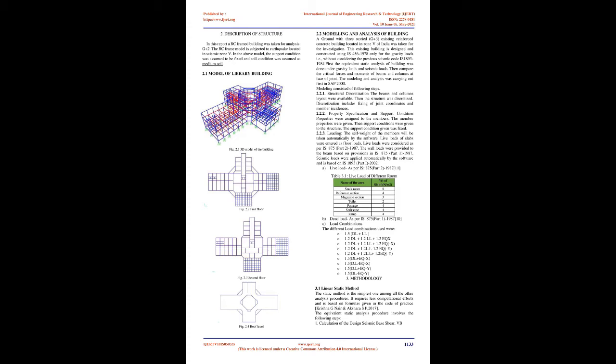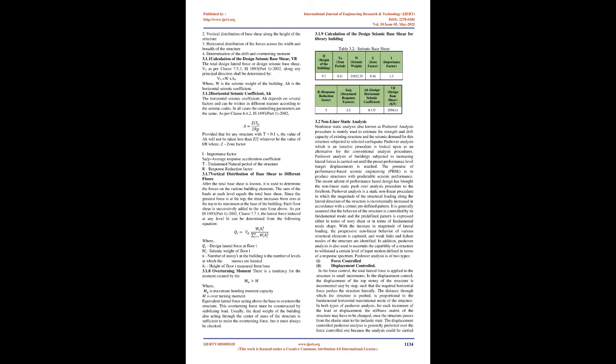In the conventional elastic design analysis method, many important aspects that affect the seismic performance of the building cannot be determined. The inelastic deformation of a building under seismic ground motions determines its structural behavior. Due to this reason, the evaluation of the building is carried out on the basis of the inelastic deformation demanded by an earthquake, besides the stresses induced by the equivalent static forces as specified in seismic regulations and codes. Nowadays, to estimate seismic demands for a building, pushover analysis is performed. It is a commonly used technique, which provides acceptable results.